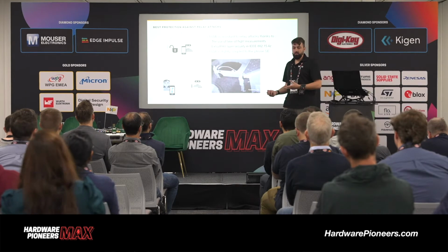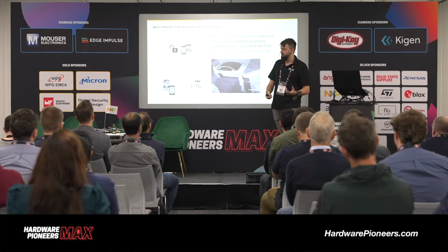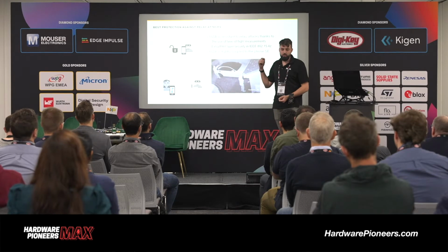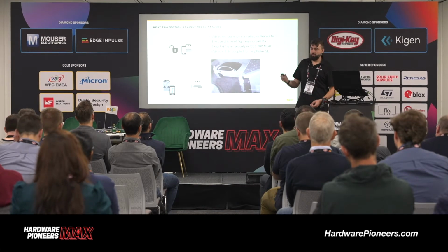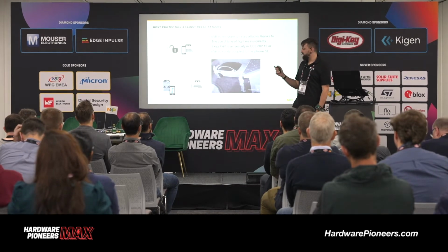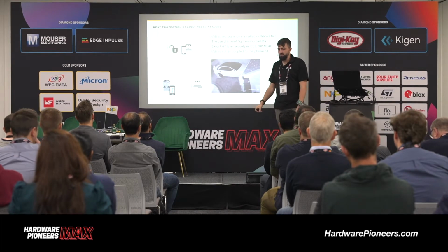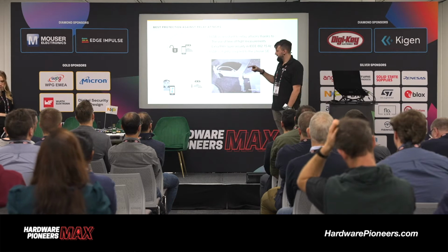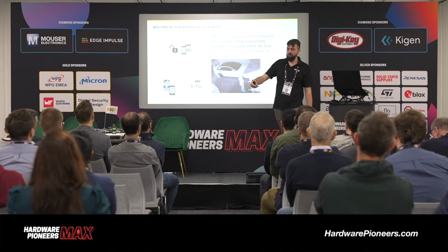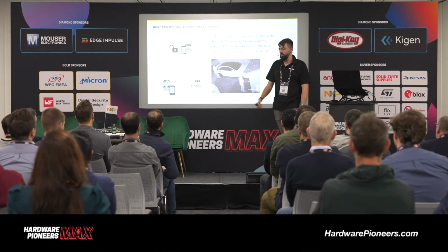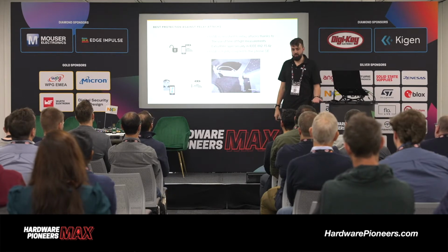Ultra wideband has a defense against that by the use of its ranging techniques. So with ultra wideband, you can measure the time of flight and then measure the distance between two devices. And if the device sees that it's further away than the signal propagation should allow, it of course doesn't unlock the car.